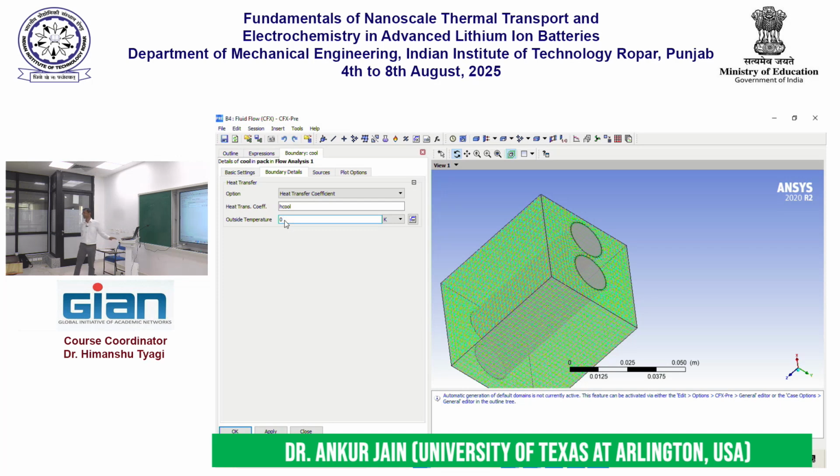Again, remember I said last time, 0 Kelvin does not literally mean 0 Kelvin. When I say 0 Kelvin, I'm simply saying room temperature, ambient temperature, so that any other temperature that I find after my calculations are over is relative to ambient temperature. So if my simulation after all of this says that the temperature here is 10 Kelvin, it really means that the temperature there is 10 Kelvin above room temperature. Okay? Alright, so here we are.